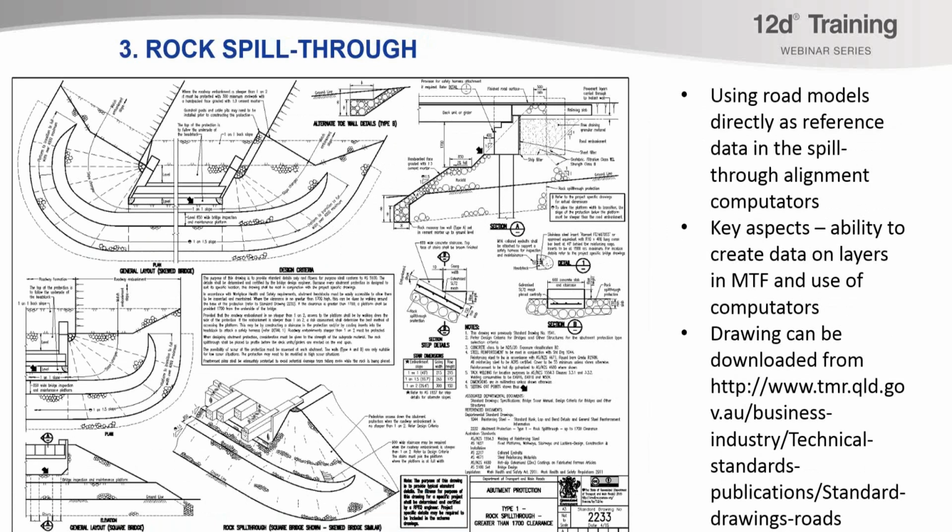But this is trying to achieve the relationships that this drawing is describing in terms of hooking onto the height of our road level, finding a point down our 1 in 2 batter slope that intersects with the height required, that 1700 underneath the soffit, for an inspection ledge. So trying to generate this point was the one that I had to have some serious thought about. I tried a few different options, but finally settled on something which I think works pretty well.